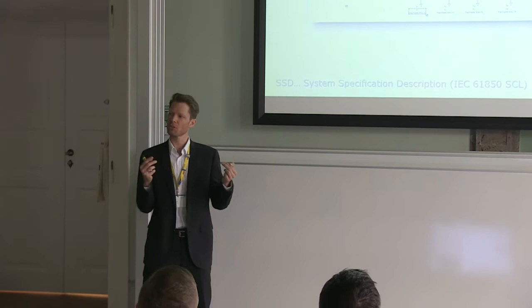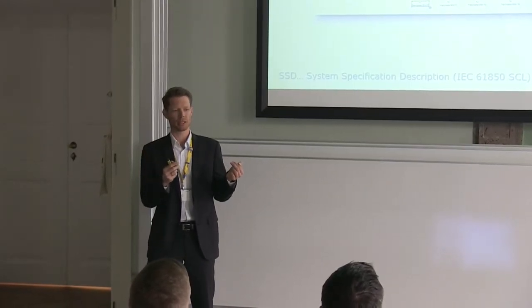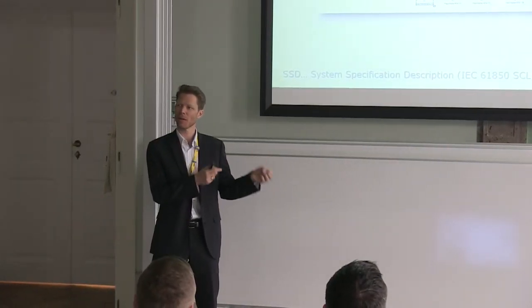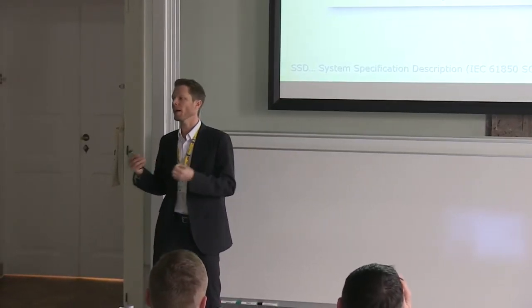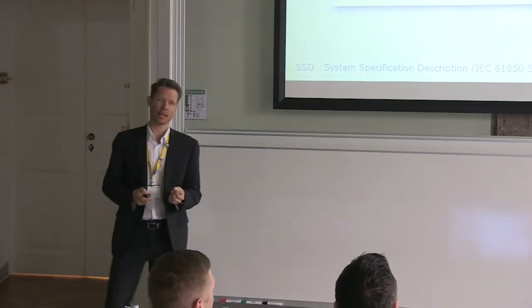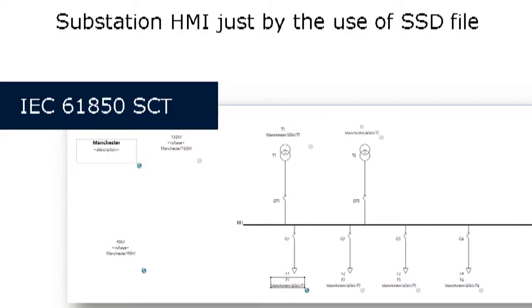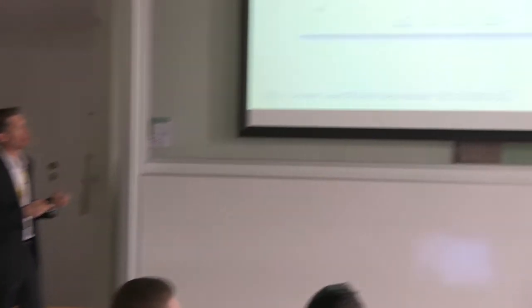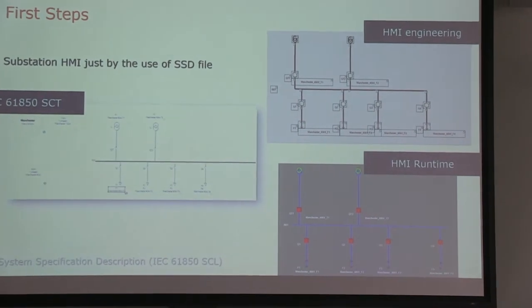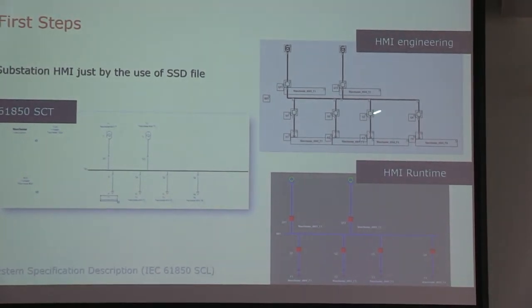We took this file, and fortunately there are tools available in this room which provide XY coordinates with the SSD file. This is the output of the system configuration tool, which provides the SSD file. Then we take this SSD file and import it into the HMI configuration tool. And this is the result of it.